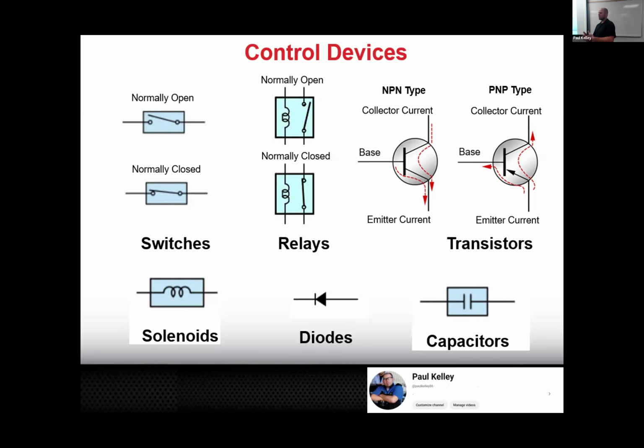And is the fuel pump getting the voltage from the ECU where it's supposed to get it? It's very possible that the fuel pump's getting the voltage and the fuel pump's bad. Or it's also possible that the fuel pump's not getting the voltage and the wiring has a problem. But it's also, however, less likely, but still possible that the fuel pump's not getting voltage because the ECM isn't providing voltage because this transistor's burned out.